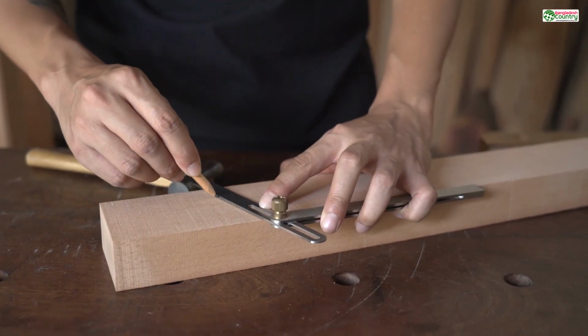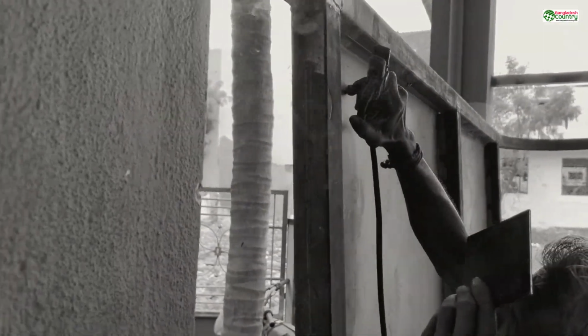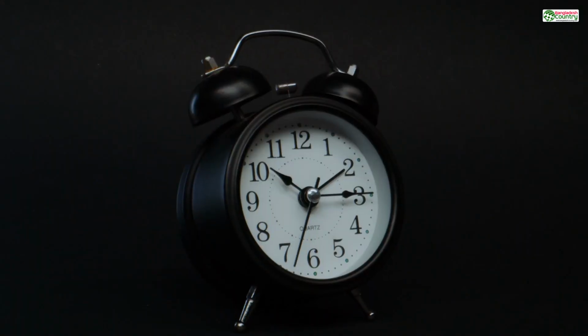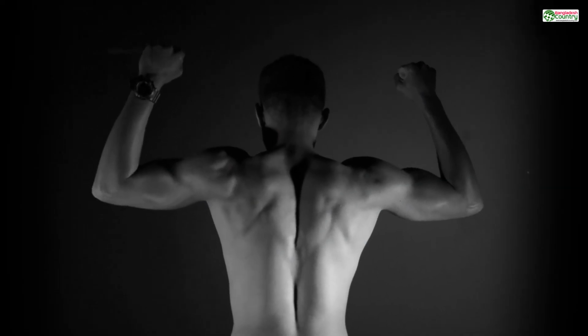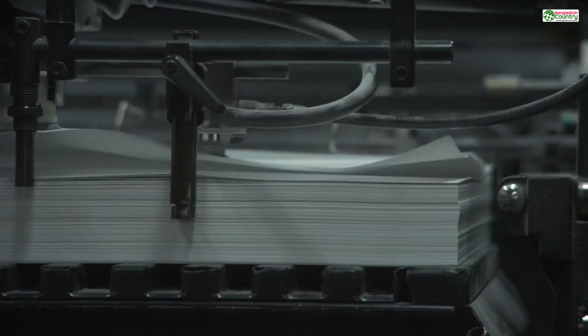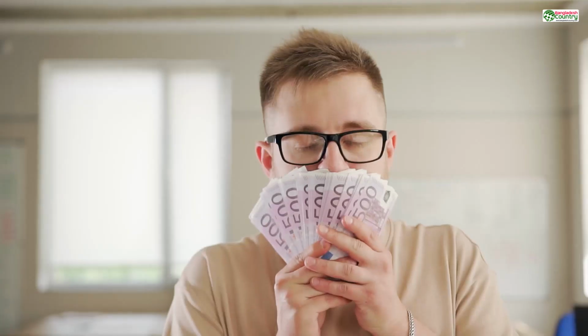Mark had made two critical errors. He designed the object based on how it looked, not on how it would be made. And he never once looked at the design guidelines for the nylon material he chose. A 5-minute check with a thickness analysis tool would have shown him that his entire design was a ticking time bomb. He had to go back, thicken every single wall, reinforce the clips, and simplify the vents. The second print worked perfectly. But that first failed print? It was a very expensive lesson in the unforgiving reality of wall thickness.